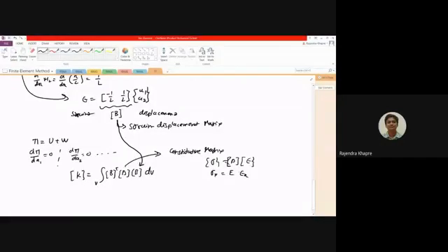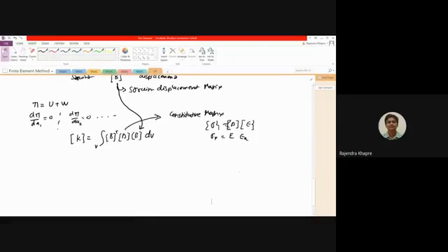If you remember theory of elasticity, you have sigma x, sigma y, sigma z, tau xy, tau yz and tau xz, all those terms will be there. But since we are dealing with only the 1D problem, this expression will be sigma x is nothing but E into epsilon x. So your D value is nothing but simple E, that is the modulus of elasticity.